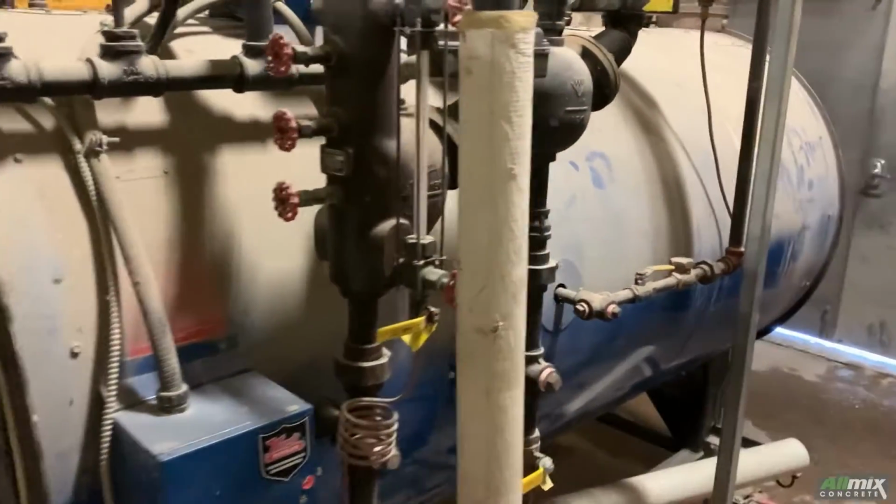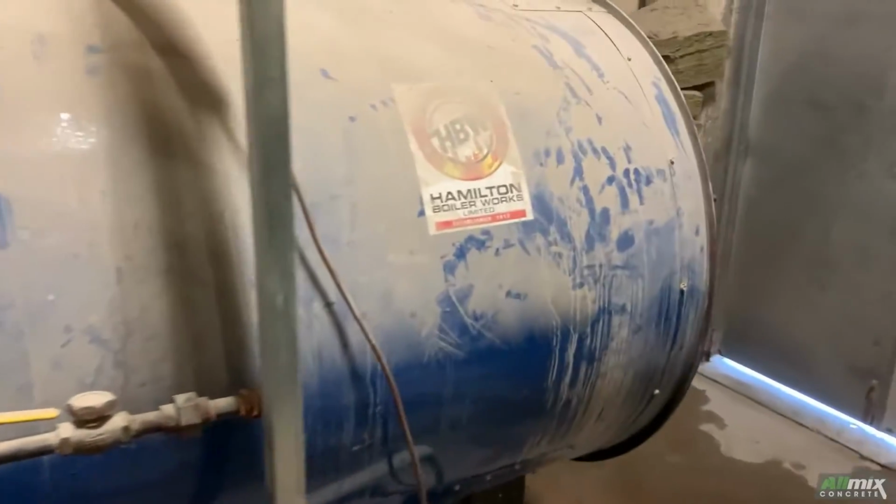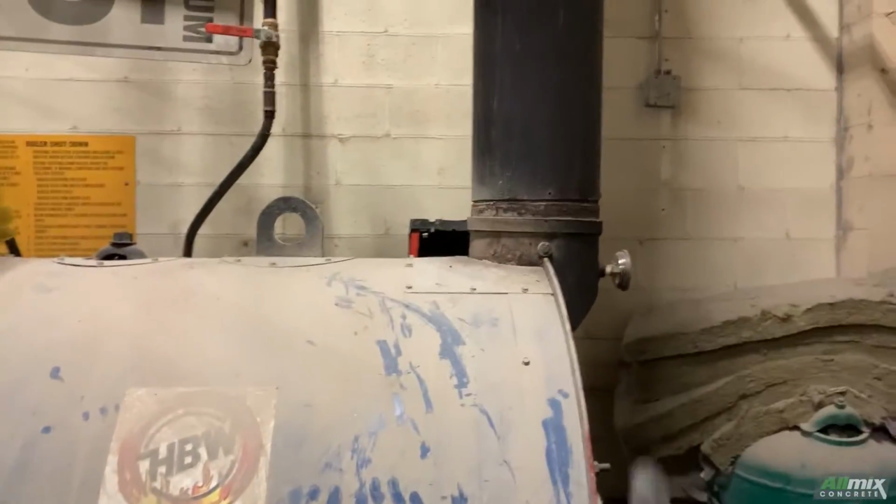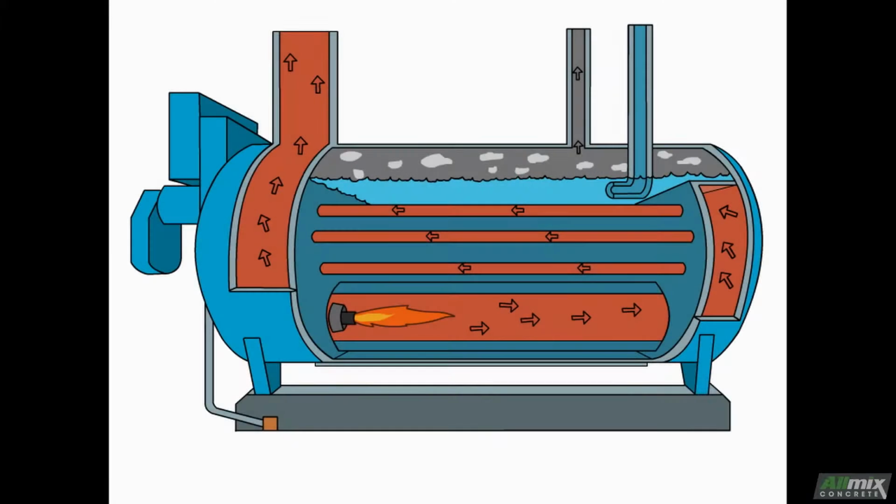So, as seen in the introduction, the furnace heat passes through the tubes of the boiler several times, and then it exits up the stack and out the building. One of the most important controls for the boiler is the water level. Too high, and water is sent through the steam lines, causing wet steam and leading to many other problems. Alternatively, if the water level gets too low, the tubes become exposed. Without the water absorbing all the heat in the tubes, the steel of the tubes become extremely hot and can lead to tube damage or failure.